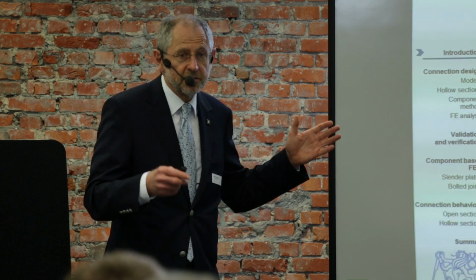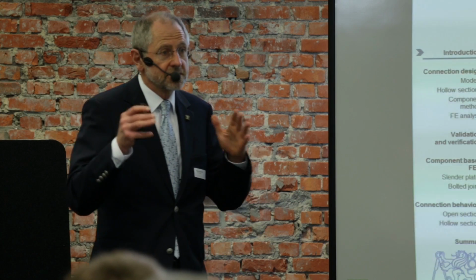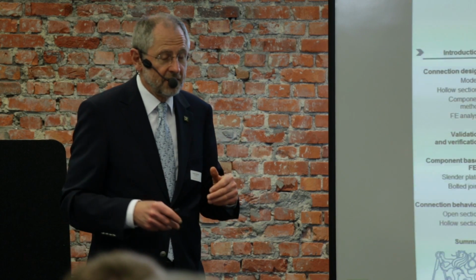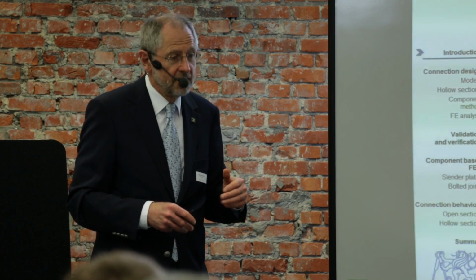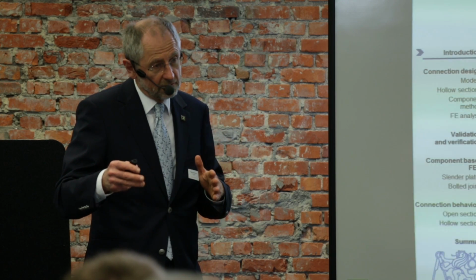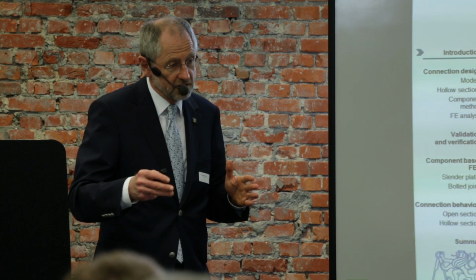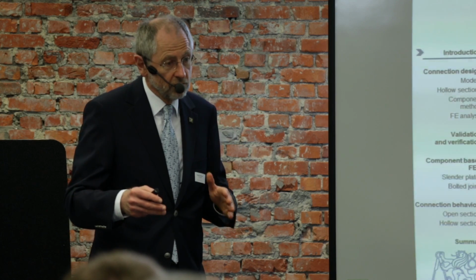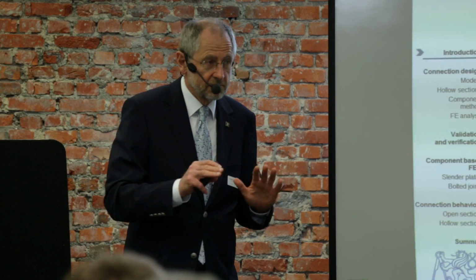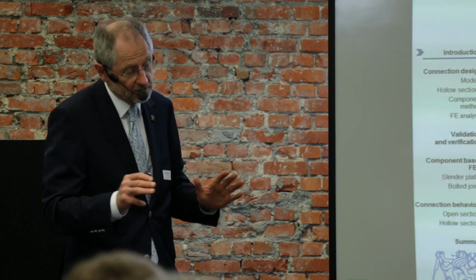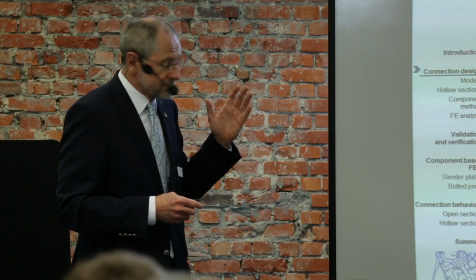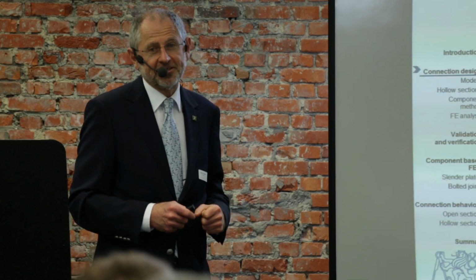Of course, especially for seismic design, it's in Eurocode 8, part 1, chapter 6.2. Chapter 6 is for steel structures, and 6.2 is two pages of questions on how to solve it, because dissipation of energy is crucial, of course. But also in connection design, we are faced with this. So this was the introduction.